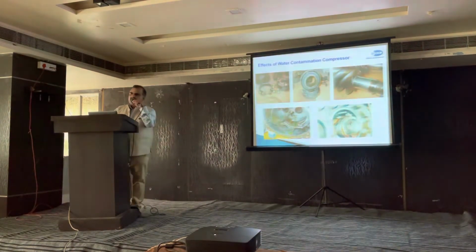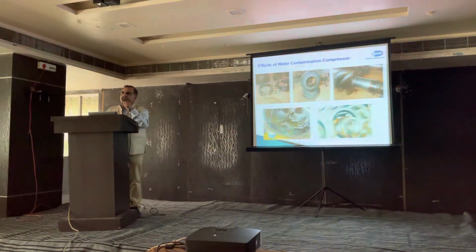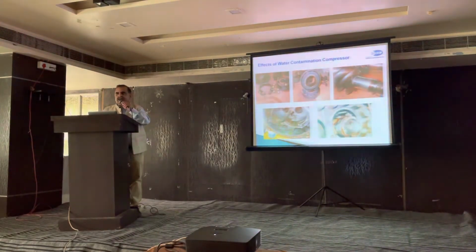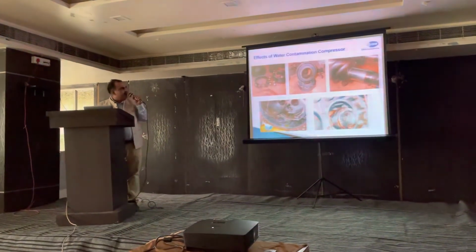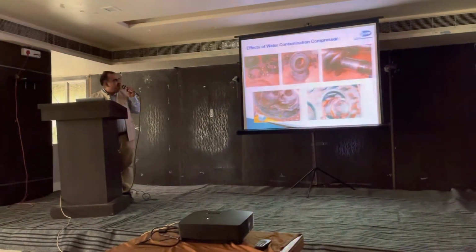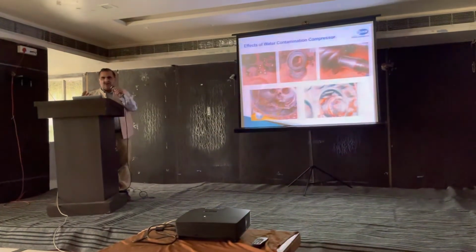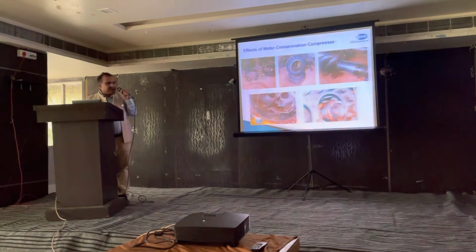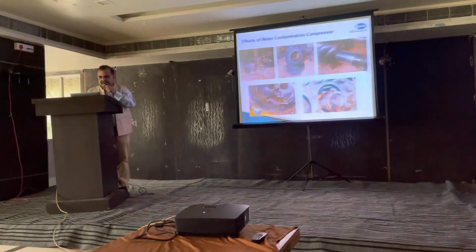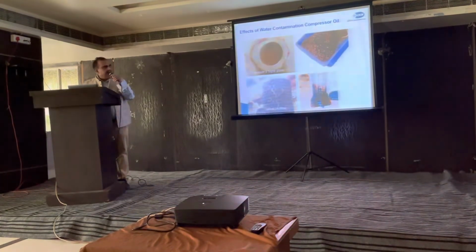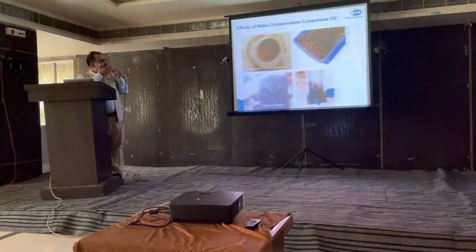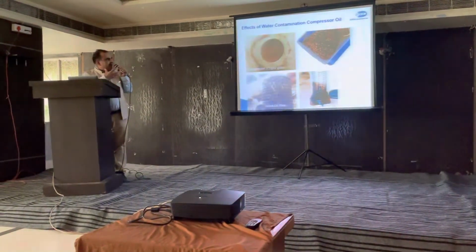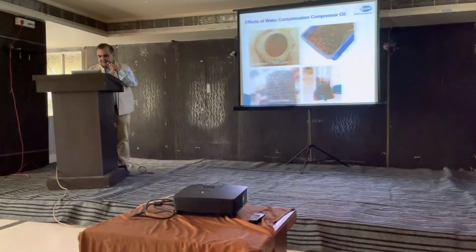These are some of the photographs which I have collected from various sources. These photographs were shared by our Mr. Dhananjay, who is mainly an expert in compressor servicing. If you see, this mixing of water and sludge formation of oil has damaged the bearings of the compressors, and the screw compressor internal parts are damaged. In a typical piston compressor, instead of the oil level, you can see it is filled with water, and when we remove the oil, it's all sludge and the oil filters are choked.